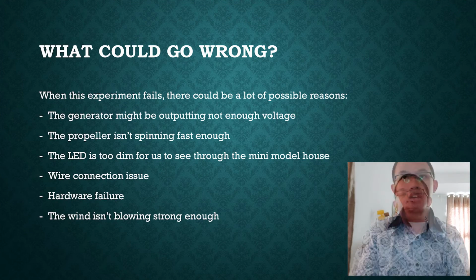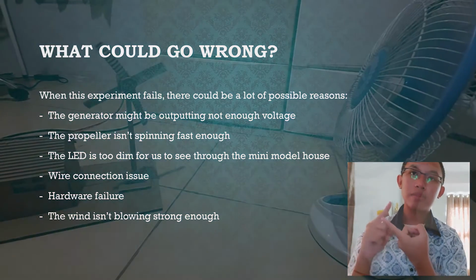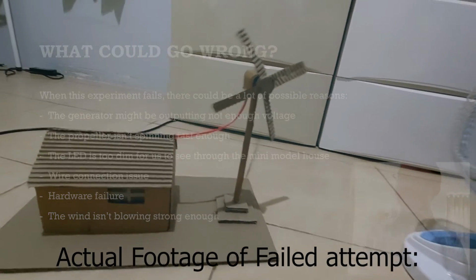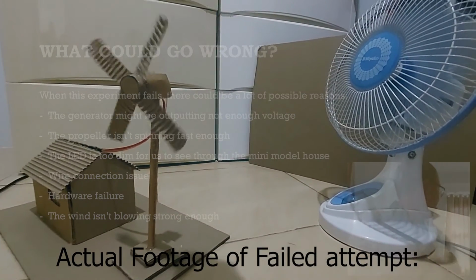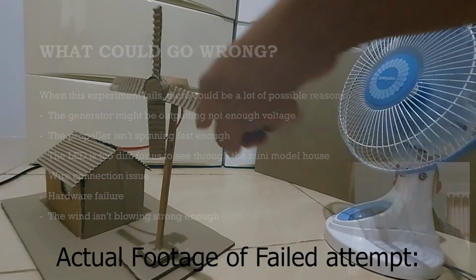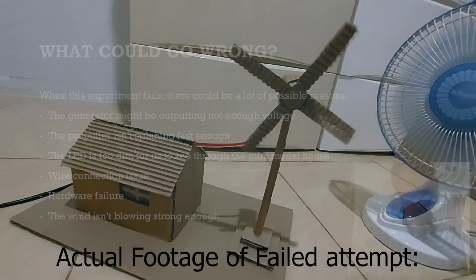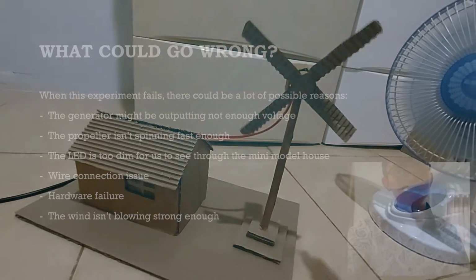Then what could go wrong? When this experiment fails, there could be a lot of possible reasons. One, the generator might not be outputting enough voltage. Two, the propeller may not be spinning fast enough. Three, the LED might be too dim for us to see through the mini model house because the plastic is quite translucent in this case. So maybe the light is too dim for us to see through the house. Four, wire connection issue. Five, hardware failure. And six, the wind might not be blowing strong enough. In case of a hardware failure, you might need to change either the generator or the LED lights, or maybe even the wire. So yeah.